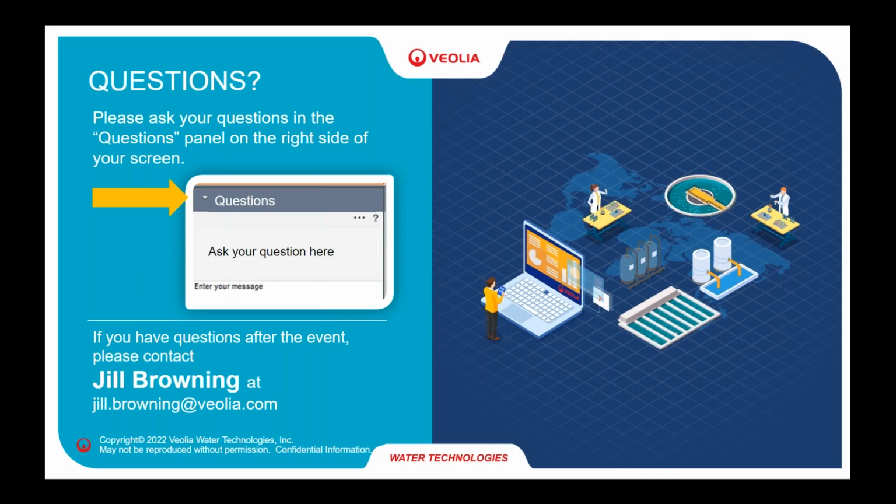It really depends. What you need to remember is that in all applications for selenium removal, you need to remove your nitrate beforehand. The big difference with the tracer is you don't need the selenium reduction biological reaction there. So you're just removing this reactor completely. You're just working as if you have your denitrification and you're good to go.